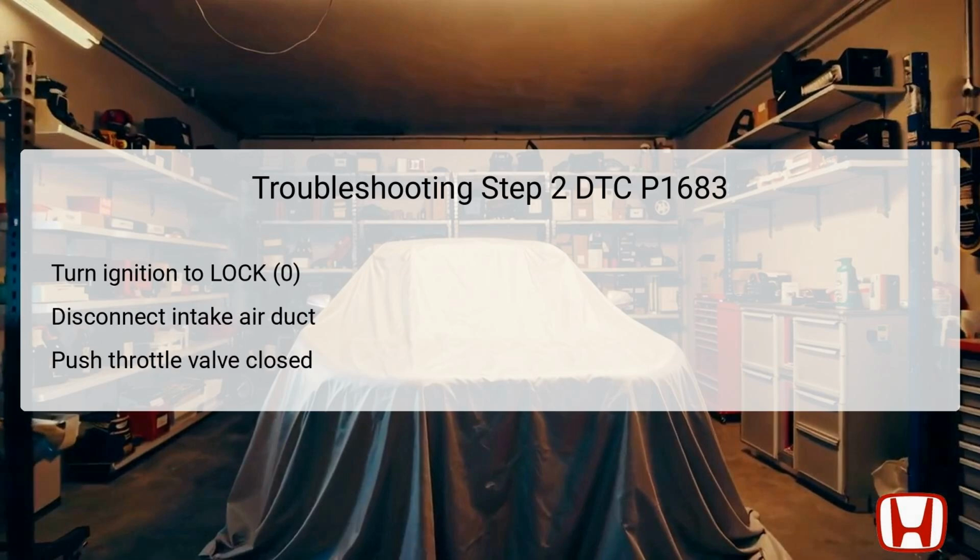In the second step of troubleshooting, the technician is instructed to turn the ignition switch to the lock 0 position. This safety precaution ensures that electronic components are de-energized before any physical inspection begins.